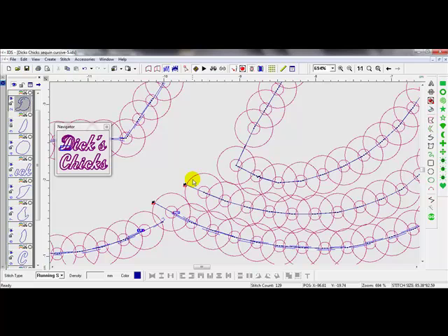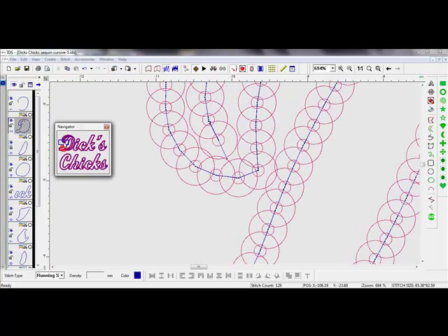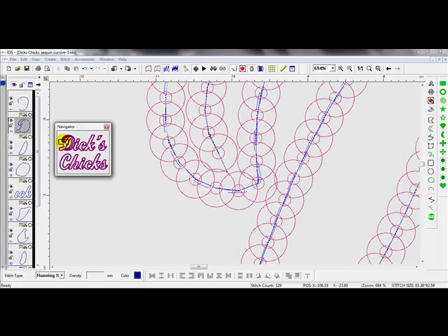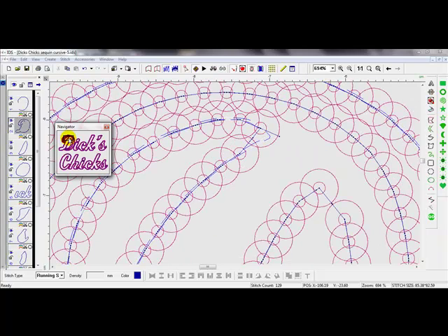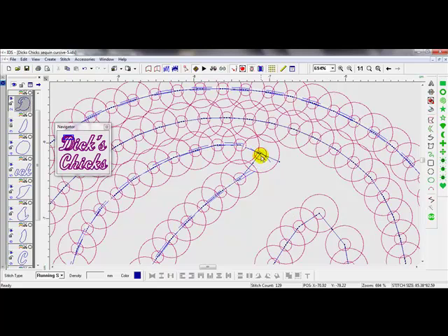Usually moving stitches is going to be your last function that you want to do, because when you move stitches it will actually lock that area. So we need to go back up to the areas that we were moving and check and see if they're going to be a problem. So this one moved back and we need to move that area or that stitch again.